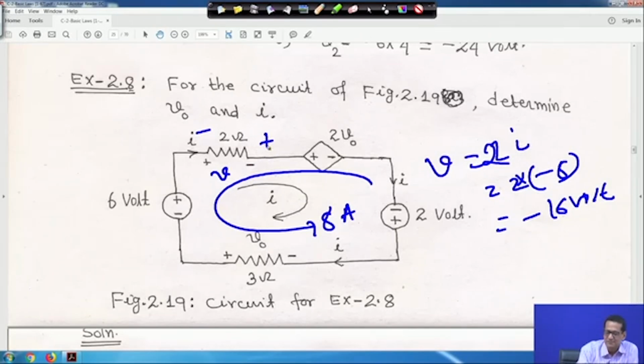So the actual polarity is this plus, this minus. Look, the current entering is a resistor, so it will absorb power: current entering into the positive terminal, and here also current entering the positive terminal. The concept has to be cleared right from the beginning, so that there will be no problem. The same philosophy will be followed for AC circuits, instantaneous polarity. If you understand the DC circuit, you will find the AC circuit is as simple as anything.